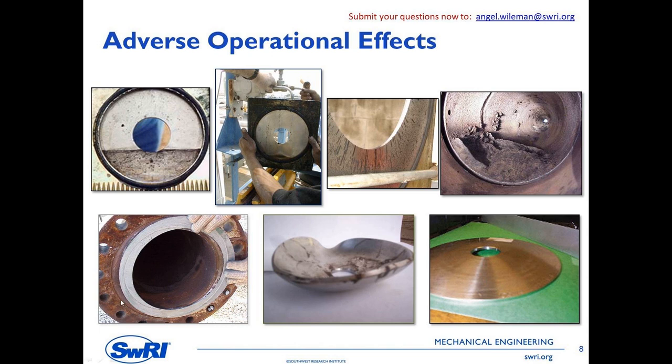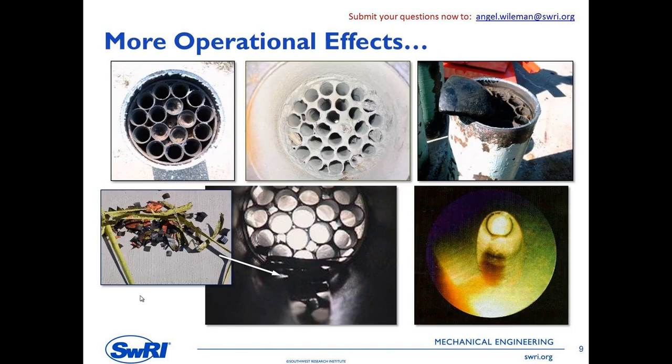There can be things like a gasket that just didn't get aligned properly. Someone used the wrong size gasket or let it unwind into the flow. Those types of operational issues can also cause errors. Of course, there's other nasty things that are out there. You go to inspect a meter and you find that your flow conditioner is completely plugged up with black powder or soot, or you've had some debris from the initial startup that was in there.